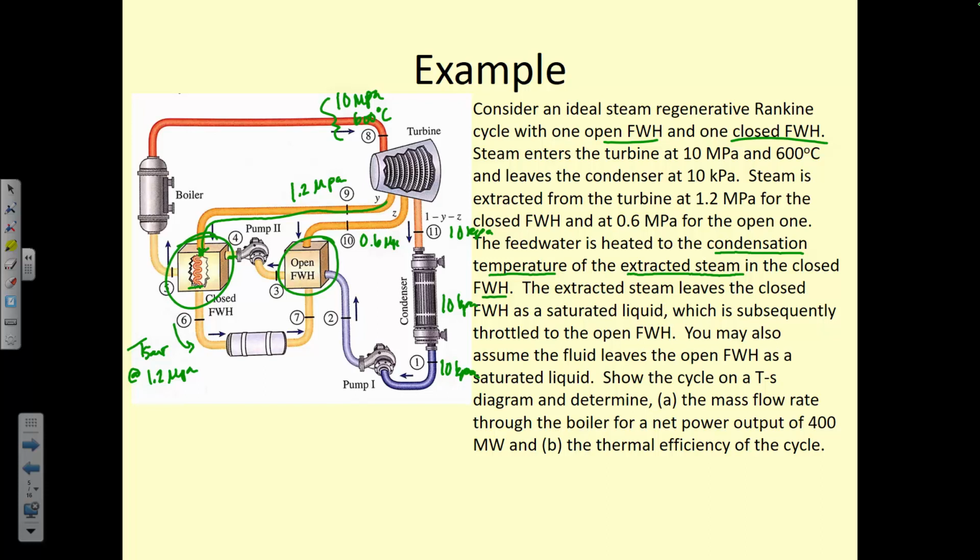So back to this. For table A6, what is the temperature beside the pressure? That's the saturation temperature. And you just said there's no saturation temperature. Oh, table A6 is superheated. So the temperature is just the temperature, and it's columns and pressures. Are you talking about the temperature at the very top of the column? Yeah. That's the saturation temperature, meaning that values at or below that temperature don't make sense in the superheated table.